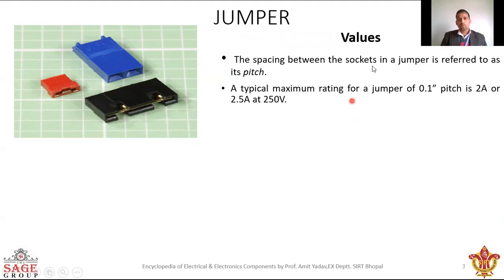Now, what are the values of the jumper? If you want to purchase any jumper in the market, then what will you say for purchasing that jumper? What are its ratings and specification? Basically, the spacing between the sockets in a jumper is referred to as its pitch. So whenever you go to the market or any shop to purchase a jumper, you have to mention the pitch you require.